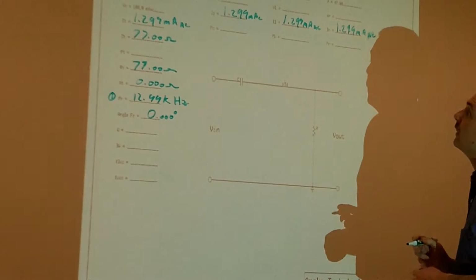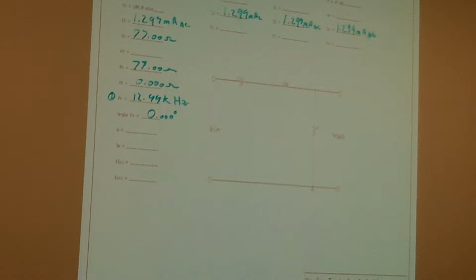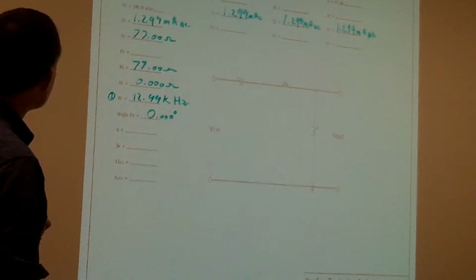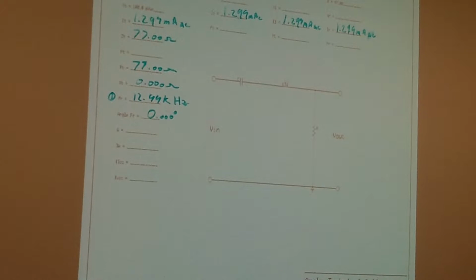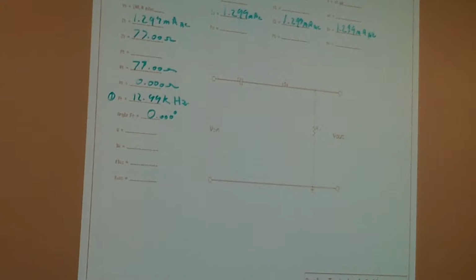All right, then what's going to be our next step? Power? Oh, I suppose we should solve for voltage on each. Yeah, I would do the voltage first. But you could do power. You actually do have enough information to do power. It'd be I squared R. You could calculate all your power because you do know I and you do know R, the resistance, so you can use the formula I squared R. But most logically, we want to stick with our voltage.